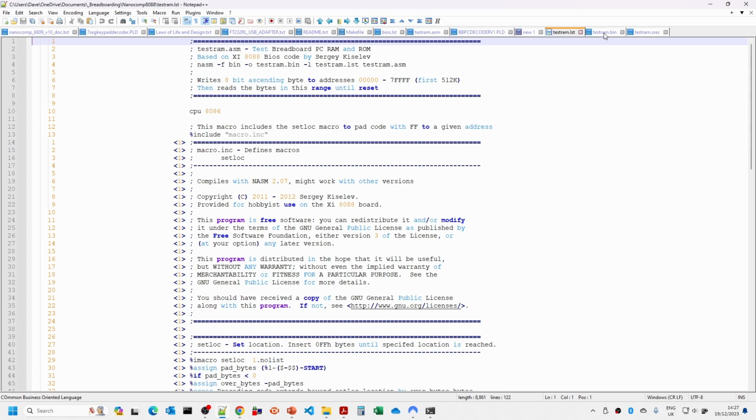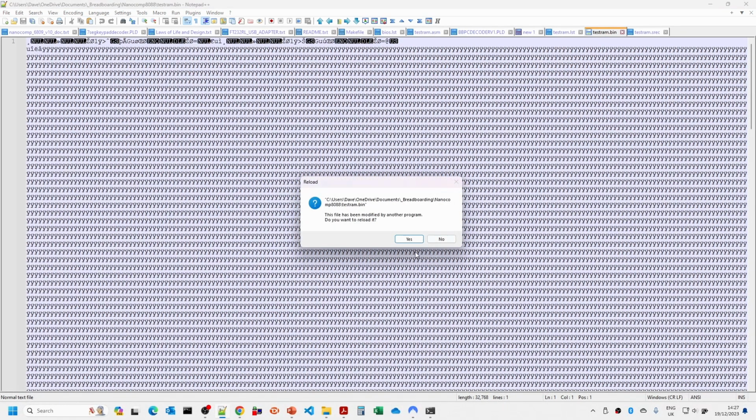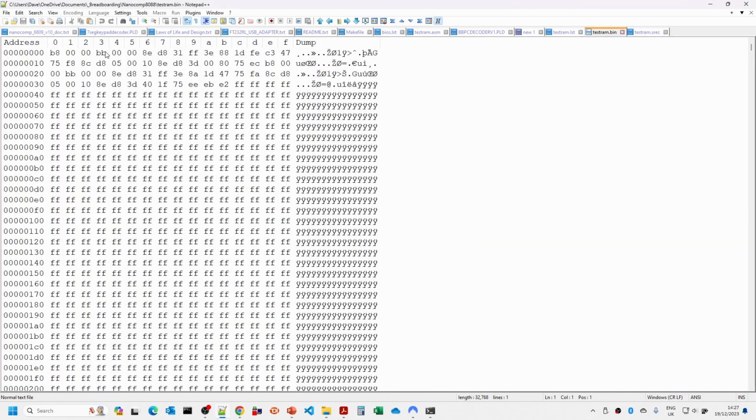So let's just have a look at the output that's produced. So this is in the hex viewer mode of Notepad++. So if you look at the end, so at 7FF0, and remember here, because the memory address for this is in fact F800, so we have to add that onto this, and so this means that this would be FFFF0, and we actually have EA 8000 F000.